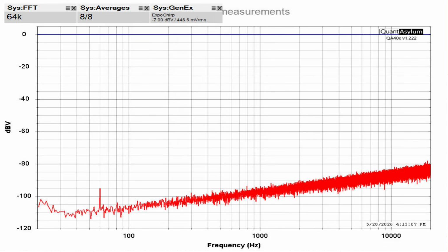In this case it's 1 volt, and you look at the output of the other channel, and the idea is that there should be no signal bleeding over onto the other channel, hence crosstalk. And you'll see on this slide that there is no 1 kilohertz signal present that you can visually see or visually measure, and you'll see the crosstalk is basically just noise.